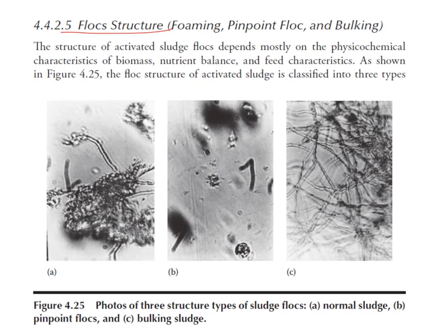However, in MBR systems, it's not really easy to overcome these foaming, bulking, and thin flock problems because these flocks not only affect the settleability of the microbial flock, but also affect the membrane fouling. So the relationship between the flock structure and membrane permeability is very important, and without properly managing these biological conditions and flock structures, the MBR process will fail.